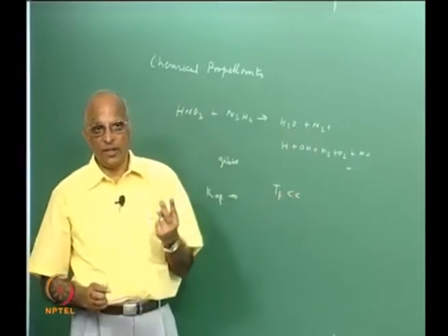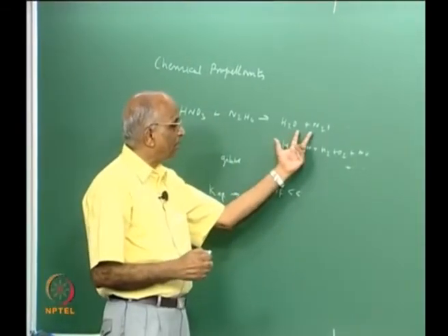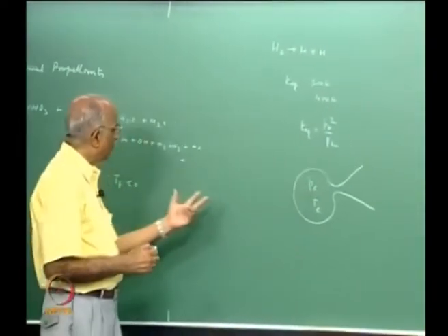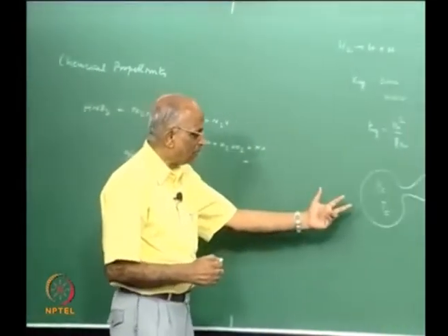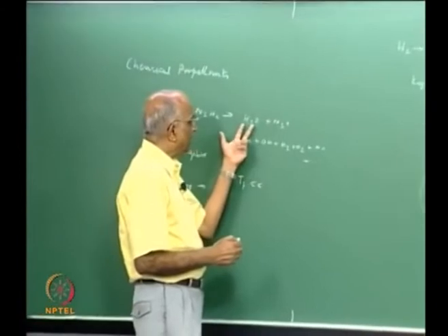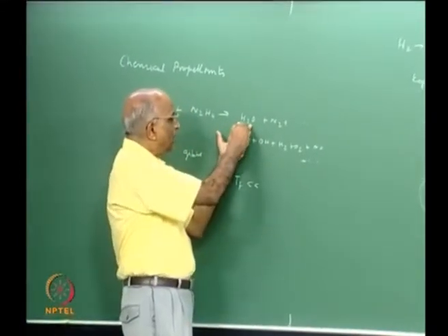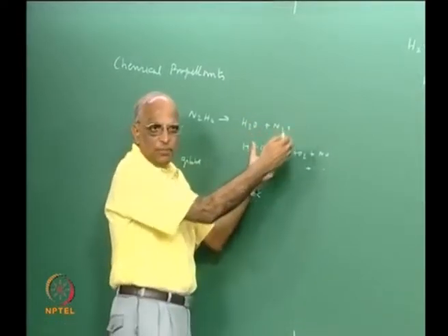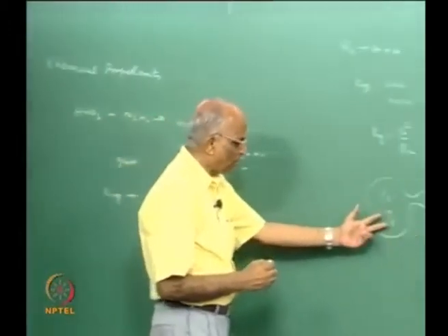We decided earlier, we said, well, if it is stoichiometric, I will have completed combustion products and I can calculate the value of Q. Once I know the value of Q, I know the specific heat distribution, and therefore I can calculate the temperature. I can also calculate the phase changes, the temperature change from the initial value to the boiling point at that phase change, and again boiling temperature to flame temperature for each of the cases. Therefore, we know how to calculate this for stoichiometry.